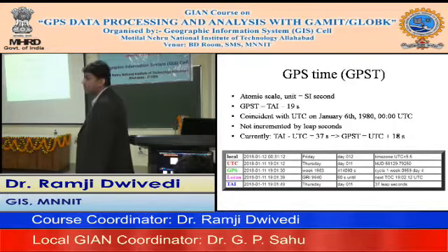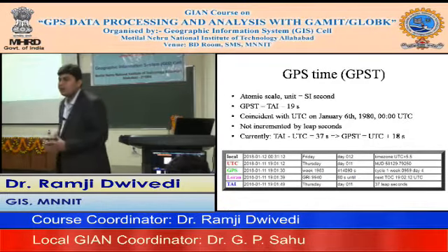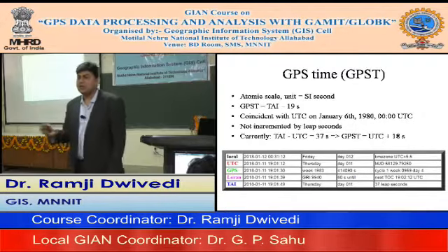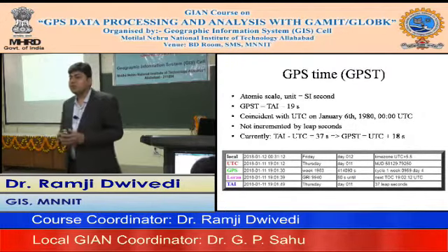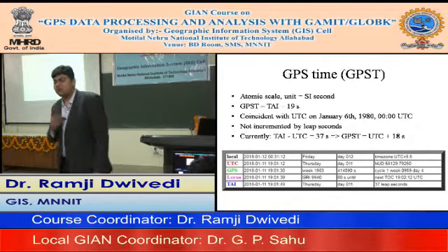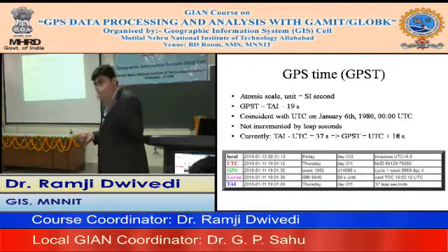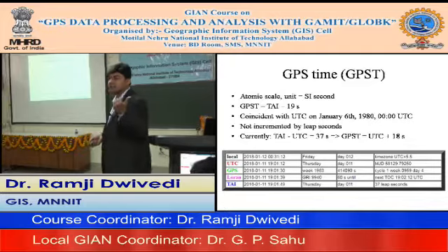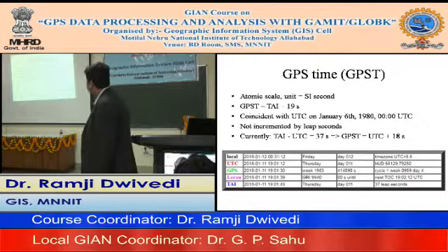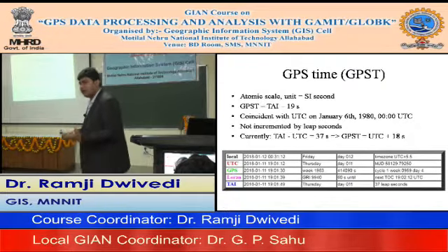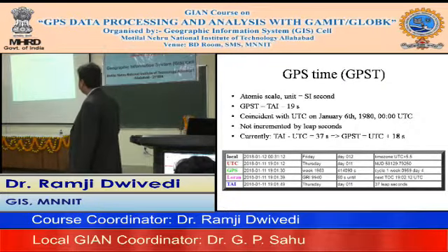Okay, so why do we need to understand the reference system? This is the summary of why we are developing a reference system for our own purpose, which is understanding the GPS, because the satellite motions are related with the geocenter of mass, Earth. That's why we need to understand the motion of the satellite in its orbital plane as well as in the Earth-centered inertial frame, because we have to relate these two systems to understand the position of our GPS station on the surface of Earth.